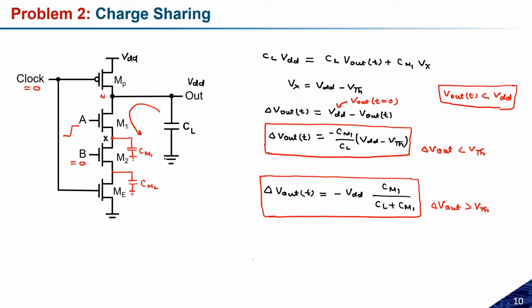Okay, so hope you got all the answers. Can we move ahead with this? And sir, this condition, delta V out less than VTH, or whether it is greater than VTH, that depends on the capacity of CMOS, right? Yes. So internal capacitance plays a major role